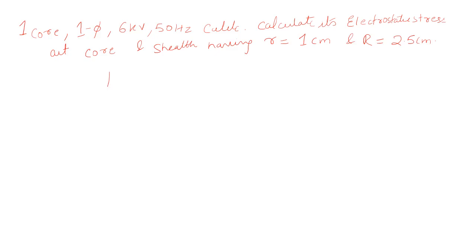So just make sure that for this quantity which you are calculating, the electric field stress, we don't want any RMS value of this. Okay, if it is given that you need to find out the electric field stress, and it is not mentioned whether you need to find out the RMS, then you always think that you need to find out the maximum stress. By default, if RMS is not mentioned, you have to think that it is a maximum stress. Okay, so maximum stress means what?